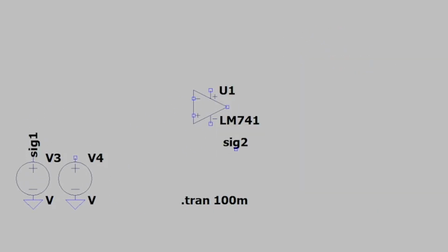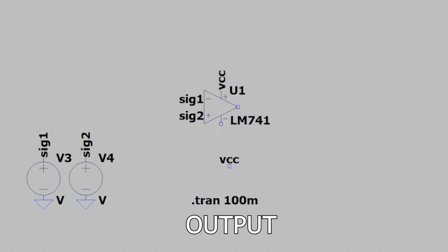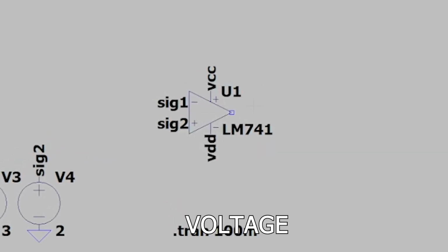If the difference between the inverting and non-inverting input signals is positive, the output voltage will go up to the positive supply voltage, since the amplifier has an infinite voltage gain. Normal, right? Well, it is not. There's at least two lies in that sentence. First of all, operational amplifiers do not have an infinite voltage gain. That's just one of the lies evil physicists tell you so that their calculations are easier to make.